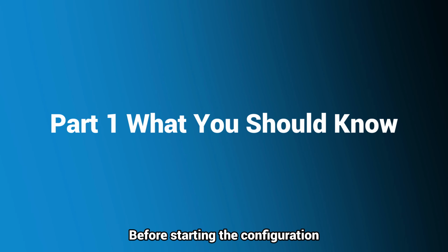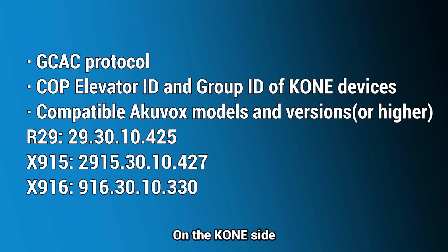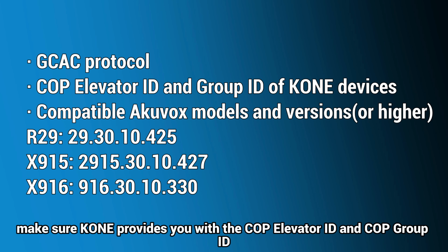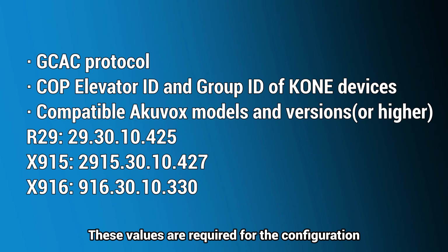Before starting the configuration, please make sure your devices support this integration. On the KONE side, the integration is supported as long as the lift control system supports the GCAC protocol. Also, make sure KONE provides you with the COP elevator ID and COP group ID. These values are required for the configuration.